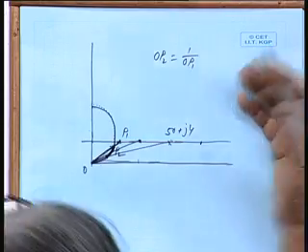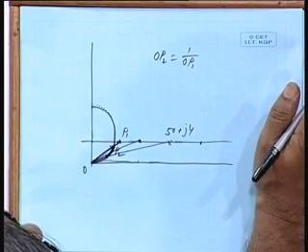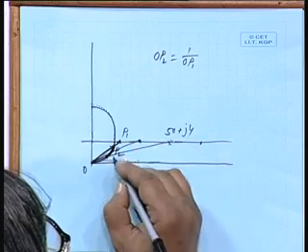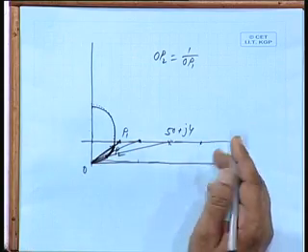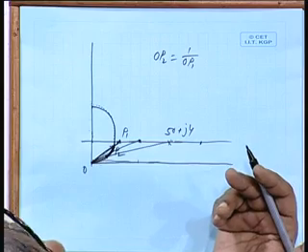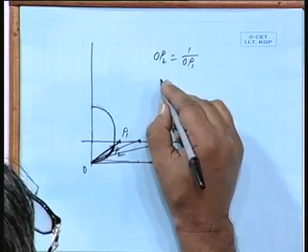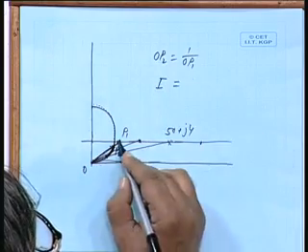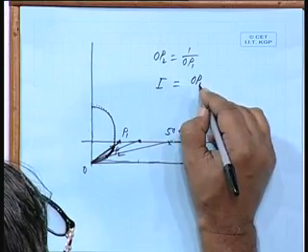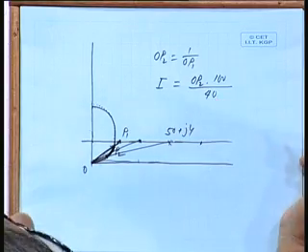I have taken a scaling factor of 40, so that has to be divided by 40. Whatever length you get on this semicircle divided by 40, and multiplied by the voltage 100 volts, that gives you the current. So, the current I is, say for example, for P1, OP2 into 100 divided by 40, the scale factor.